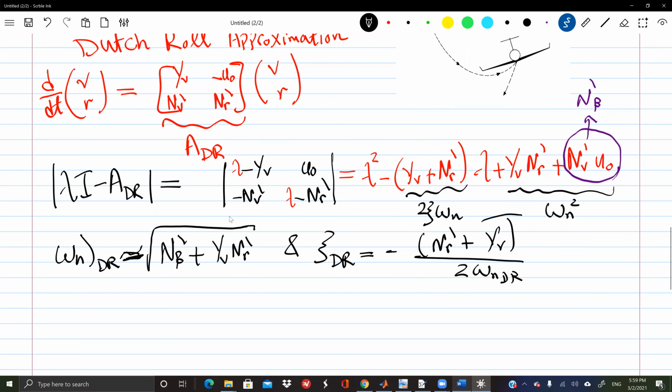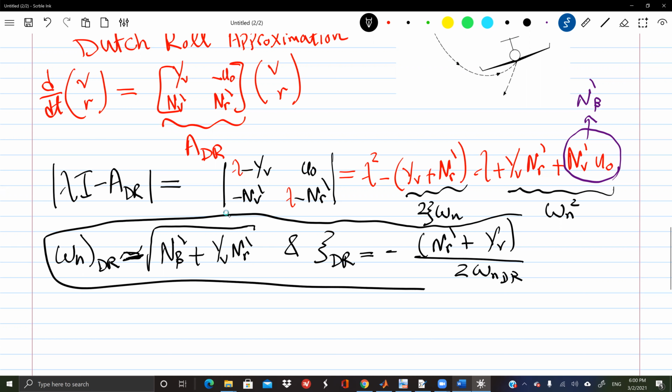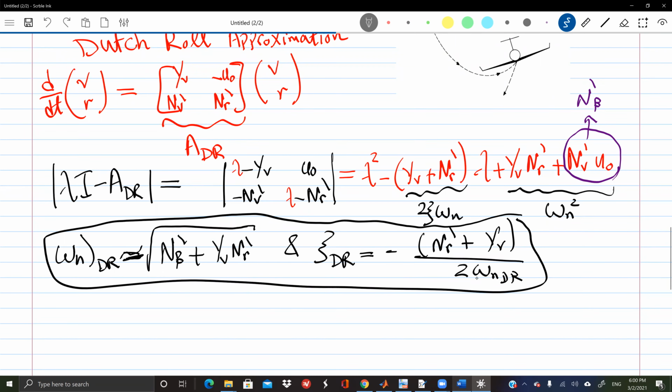Why do we like to get approximations where it's not hard at all to get the exact values, it's just the eigenvalues of a 5 by 5 matrix? I get it in less than a second in MATLAB. Why? Because these analytical expressions are illuminating. They will tell us a lot about the physics of flight. Let's look at that. Omega n is the natural frequency. Always recall the mass spring system. Mass spring system, omega n is what? Square root k over m.